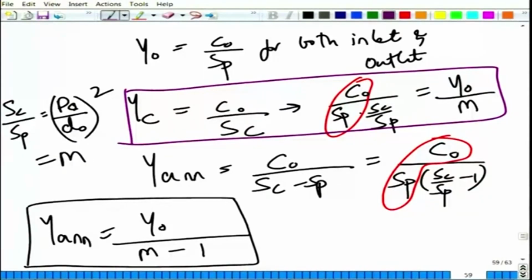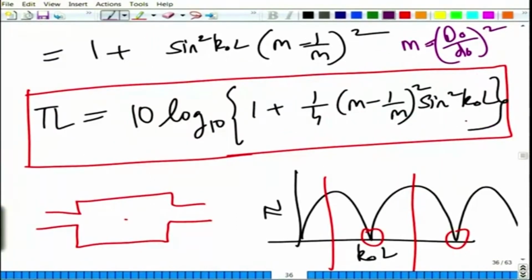If you go back to our slide somewhere here, M and L, and frequency of course is there, but in the Maple expression that I just presented, we saw as many as M, the expansion ratio, then here you have 3 other variables, the chamber length capital L, extension length L1 and L2, and the L3 is fixed of course once you select the other two, and area expansion ratio M and Y naught. So, we have a bunch of variables to play around with, and this looks to be a rather complicated expression. So, the best practice then is to derive the transmission loss expression for a general element.